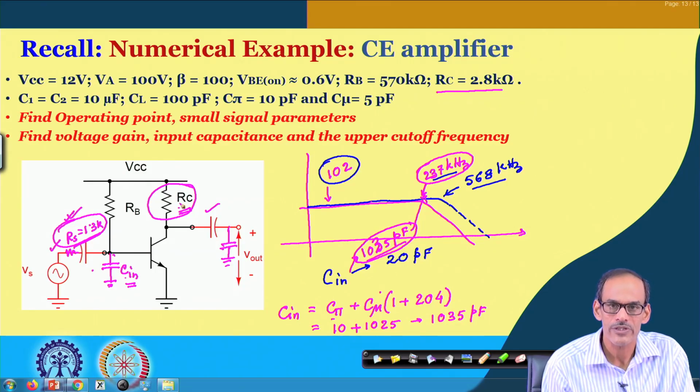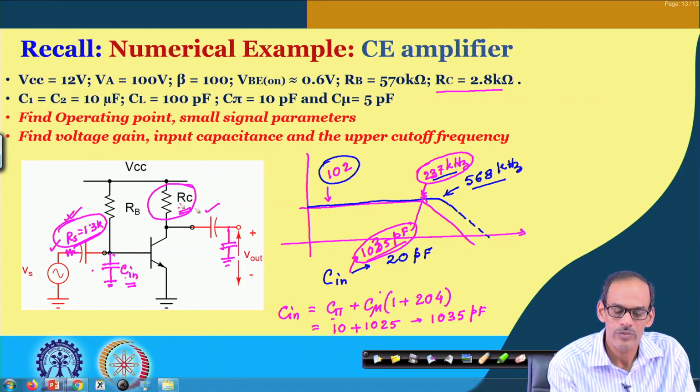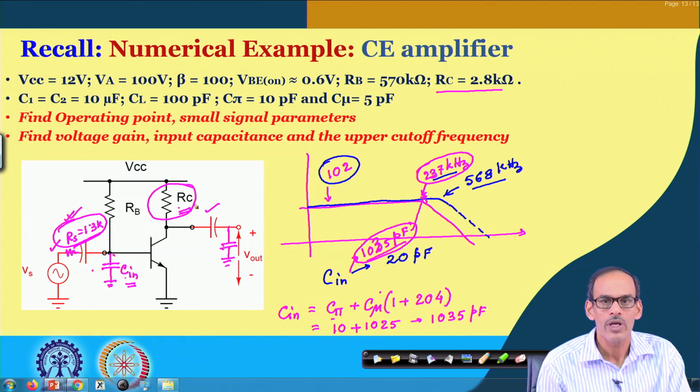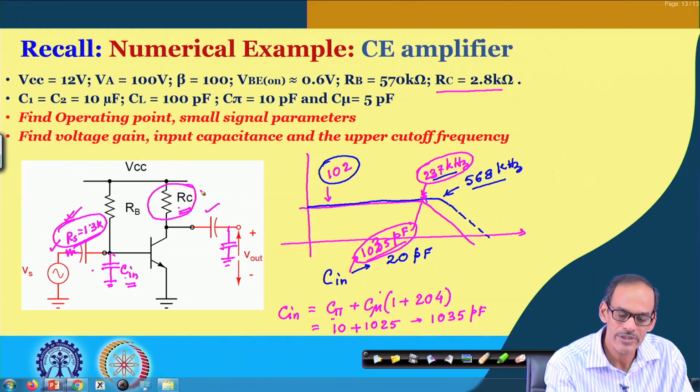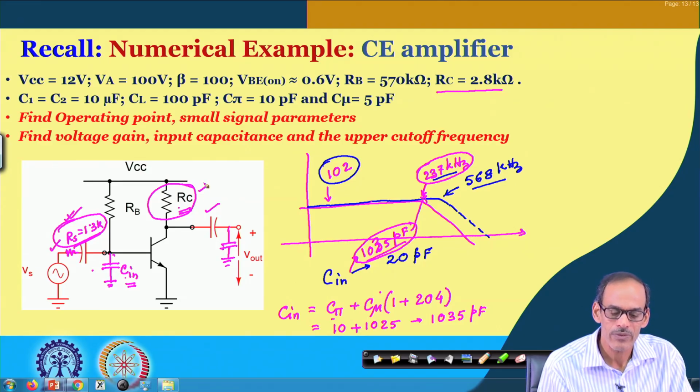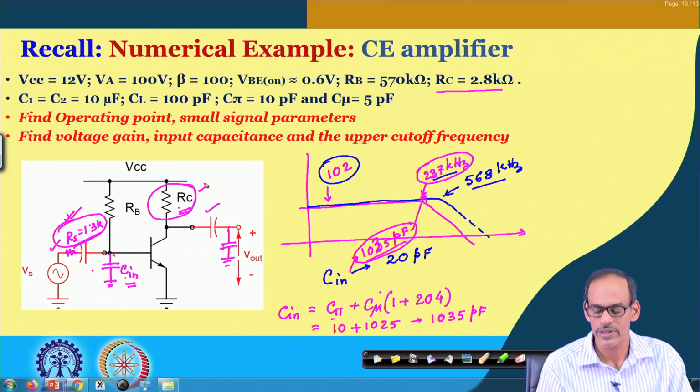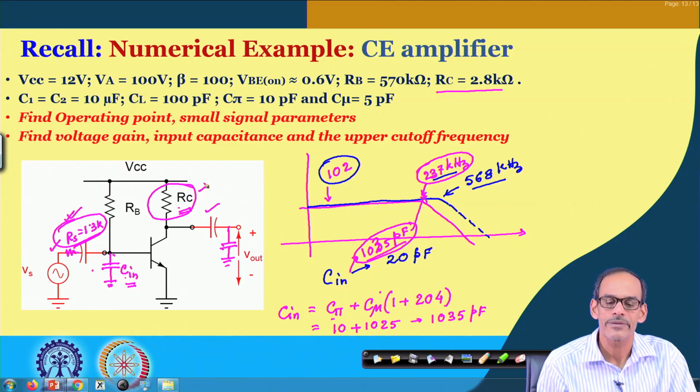With a cascode amplifier, the output resistance is quite high compared to this passive element. To demonstrate this capability, let us consider a different situation. Instead of R c, if you put some active circuit there, then the advantage of the cascode amplifier for enhancing the gain will be quite prominent.